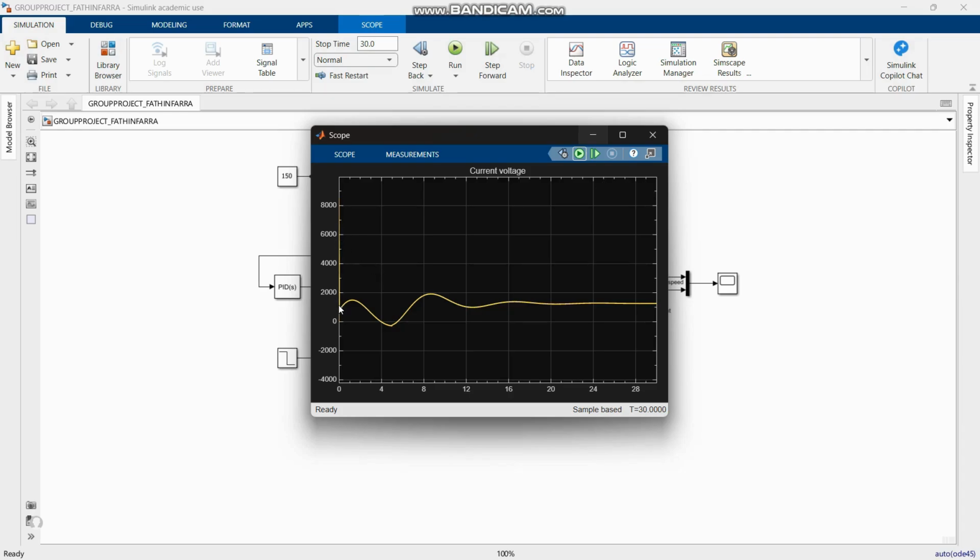The model includes a solver configuration block because Simscape physical networks require a solver to calculate the electrical and mechanical equations. In this simulation, no algebraic loop error occurred, so no special algebraic loop handling was required. For the disturbance, the step block has zero crossing detection enabled.